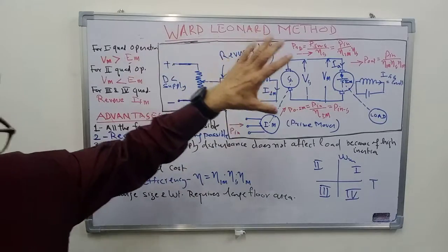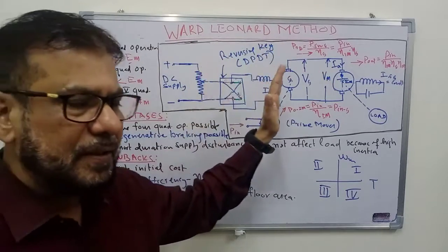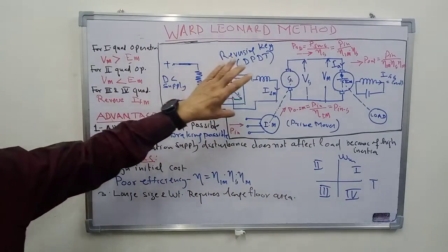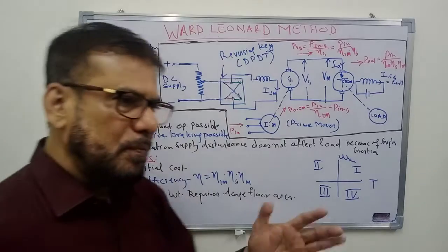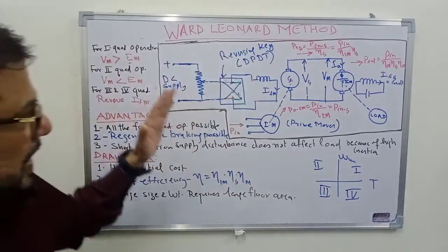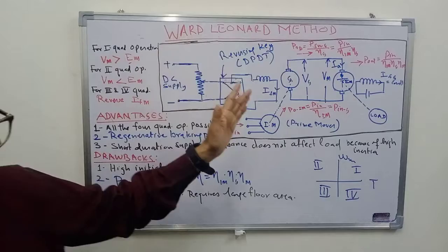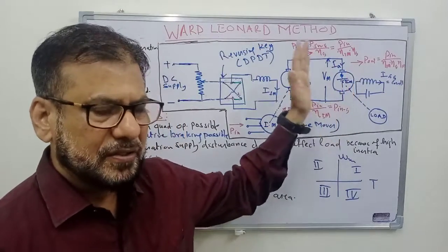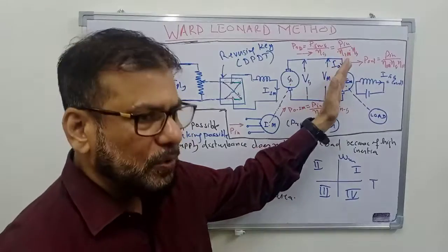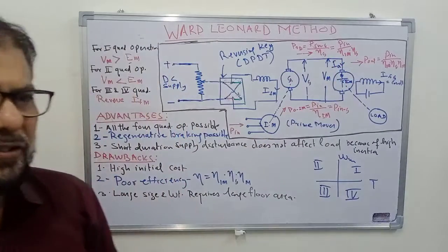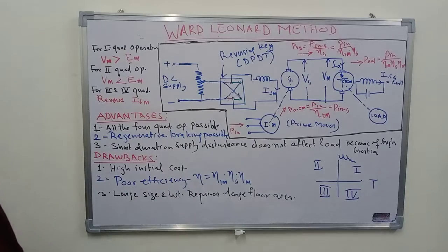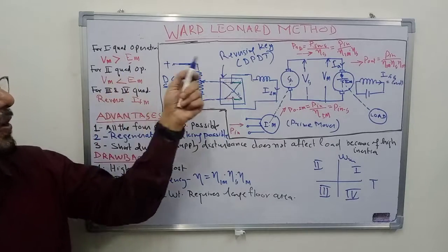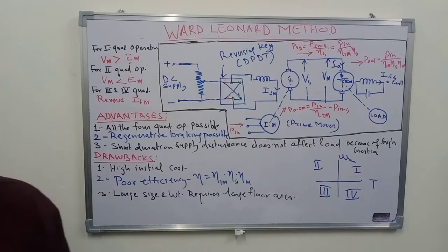We may have a control rectifier which is given 3-phase supply, or you may have some DC chopper with input DC supply, or you may have a combination of these converters, that is we have 3-phase supply, then we have a rectifier, and then we have a DC to DC converter, that is chopper, to get a variable DC supply here. So all these schemes we shall discuss in the upcoming classes. So this is what is known as Leonard scheme of speed control of DC motor.